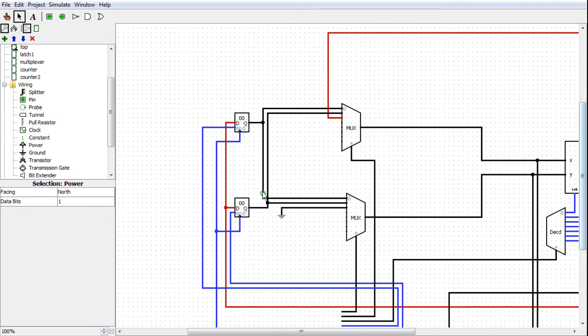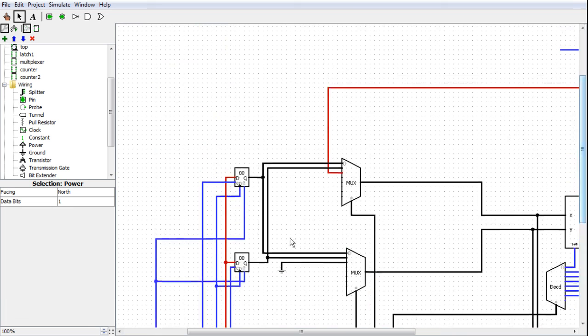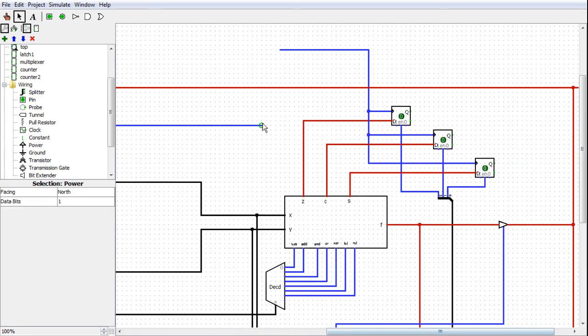And we want to be able to reset the CPU to some starting state. So connect the reset pins together. We want to reset those to 0. What else? We want to reset definitely the... Stop it. Want to reset these ones up here to 0. Where is it? These guys. Off by a little bit. There we go. You go to 0. You go to 0. And you also go to 0. Good.